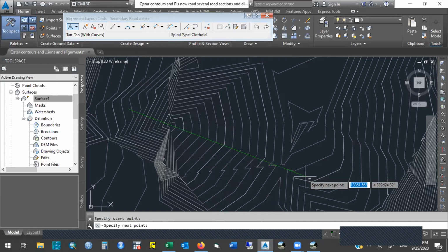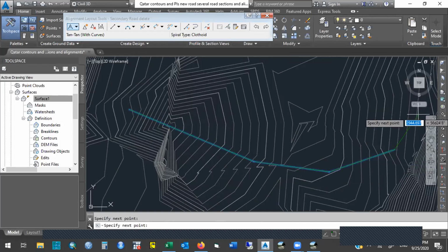So when you are going with a specific alignment, I'm doing something horrible, right? I'm doing exactly what you are not supposed to do with an alignment. I'm going all the way up to the top of the mountain and all the way down, and then again all the way up. You typically do something else. You stick to the contours. I will explain that later.